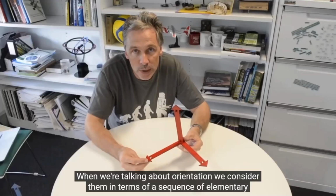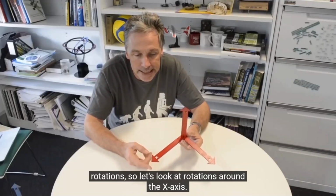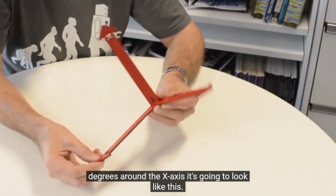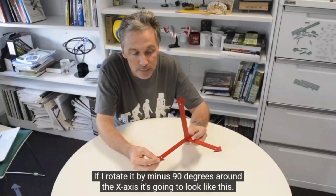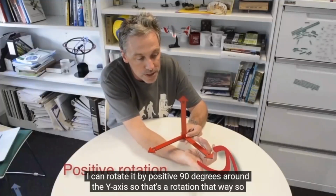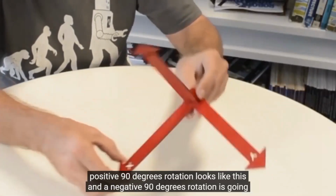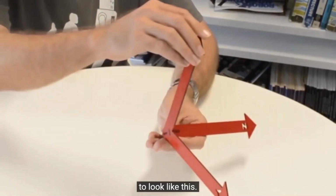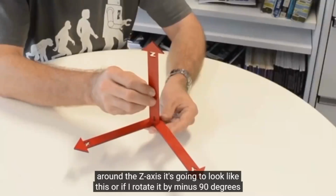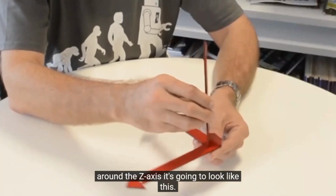When we're talking about orientation, we consider them in terms of a sequence of elementary rotations. So let's look at rotations around the x-axis. So this was the positive rotation direction. So if I rotate this coordinate frame by 90 degrees around the x-axis, it's going to look like this. If I rotate it by minus 90 degrees around the x-axis, it's going to look like this. I can rotate it by positive 90 degrees around the y-axis, so that's a rotation that way. So positive 90-degree rotation looks like this. And a negative 90-degree rotation is going to look like this. Now, positive rotation around the z-axis is this way, so if I rotate this frame 90 degrees around the z-axis, it's going to look like this. Or if I rotate it by minus 90 degrees around the z-axis, it's going to look like this.